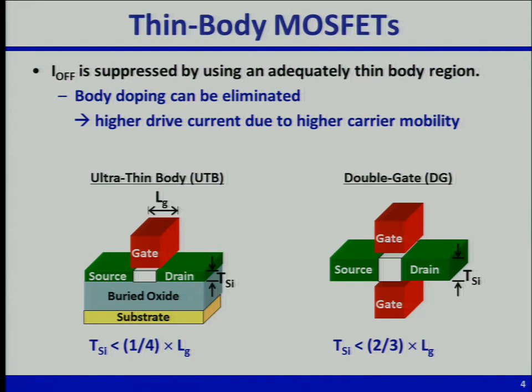2.5? Okay, so what happens with silicon if you make it physically that thin, you get quantum confinement effects. So it's like you have a buried oxide underneath and a gate oxide on top, so it's like a high band gap material sandwiching a small band gap material. So you basically have a quantum well for electrons and holes in the silicon. And so you start to see quantum confinement effects become significant if the body is thinned below 5 or 4 nanometers.